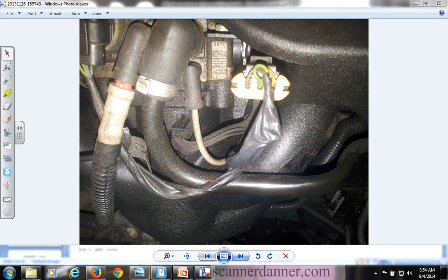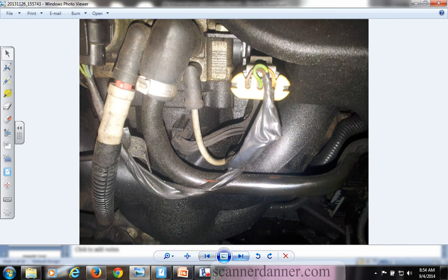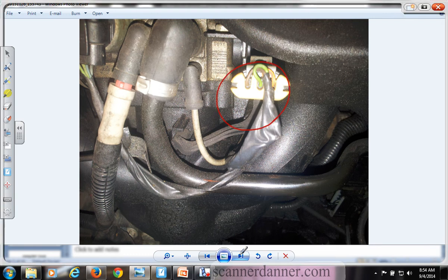Split. Believe it or not, it's not split. It looks like a crack developing in there. There was no leak on this hose to the MAP sensor. That's pretty cool, isn't it? That hose was getting pulled in, right? So what happens is we're trapping vacuum up in here. That would make sense then during a snap throttle when we lose our vacuum in the engine. Our vacuum levels would be changing very drastically.